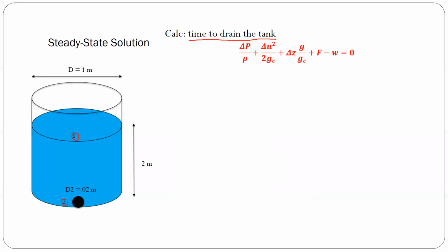Anyway, if we're going to assume that the fluid is inviscid, there are no frictional dissipation, then we will omit this frictional term here. Okay, and in this sketch, in the problem, there's no mention of any work like that from a pump or whatever. Okay, so we can eliminate the work term. So we ended up with this, but there's some term that we can still omit.